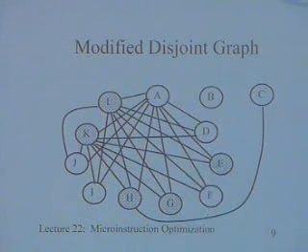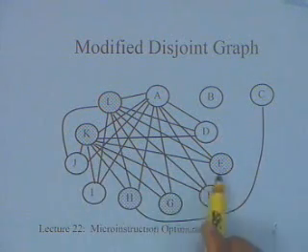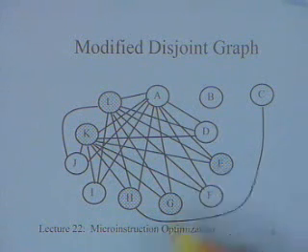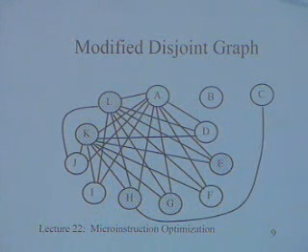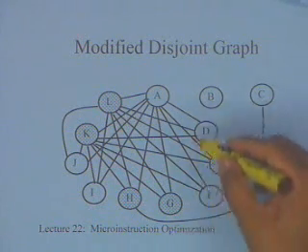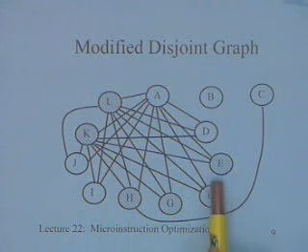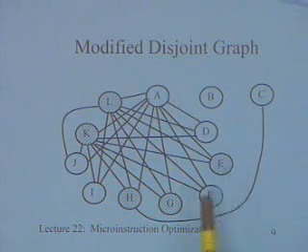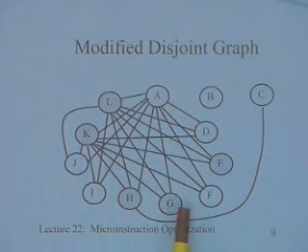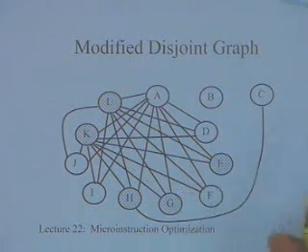if you are grouping, when I am doing my clique partitioning, or when I am doing my clustering, at that time if I merge two control signals which are both, let's say in this case, nodes of this type, then I need an additional no-op. But if I merge this with a control signal which doesn't have a default value, okay, so I can take care of these, whether what is the nature of this, and then I can make an estimate based on what is required, how it will help in reducing my control signals. So doing the same thing, taking care of this, I can do my partitioning.